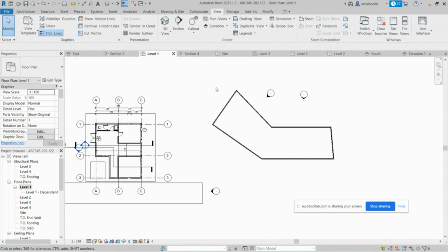Inclination in the view can be done, no problem, but it's not giving you information. Now we said from the beginning that working drawings or construction documents are not architectural representation. They are an actual reflection of dimensions, materials, proportions, and other things that tell the constructor what to follow exactly in order to have the building as drawn. So if you put a tree in front of the elevation, this tree will hide useful information, right? In addition, if you are not projecting things that are 90 degrees from your view, this is not useful.